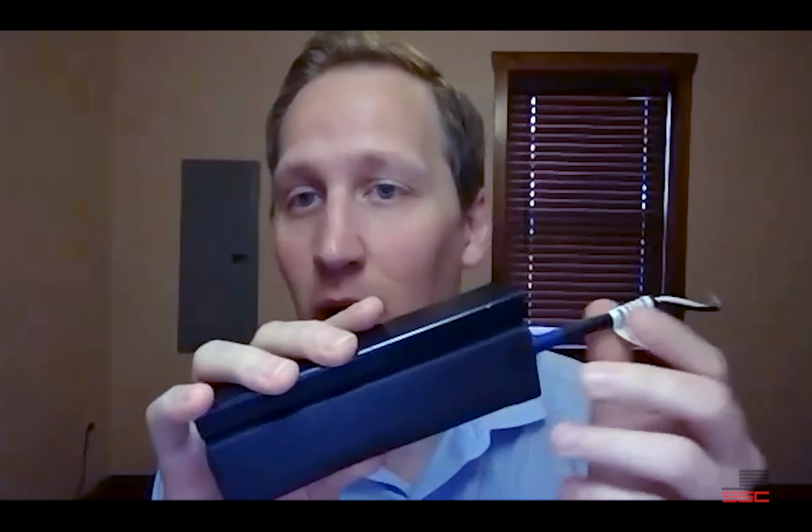So looking at the two of them, you wouldn't be able to tell apart from the product label. They will look identical from the outside, the ME120 and the MGO. The difference is on the MGO, the contacts are circular, they're round inside of here. What that means is that I'll get an activation not only from the front here, but also from the side. So you can get a side activation. So the MGO, we really encourage for use on swing gates. The ME120, we would encourage for use on slide gates, and then a few other applications in between there, depending on what it is.